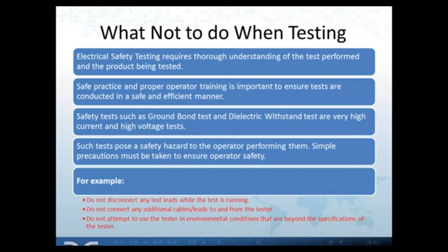For example, while the test is running, the operator should not disconnect any test leads. This can pose a shock hazard to the operator. This can also be damaging to the tester itself or the device being tested.